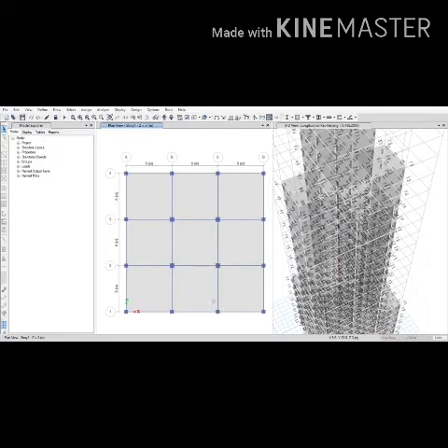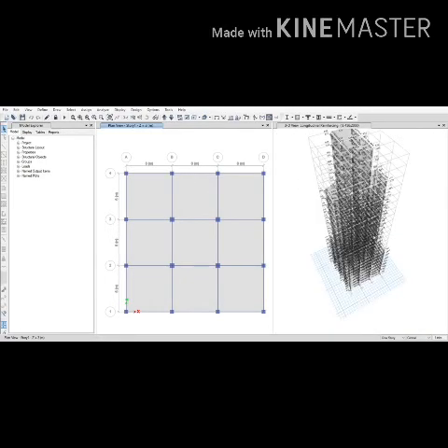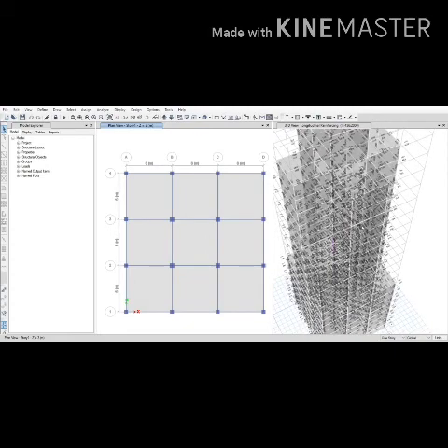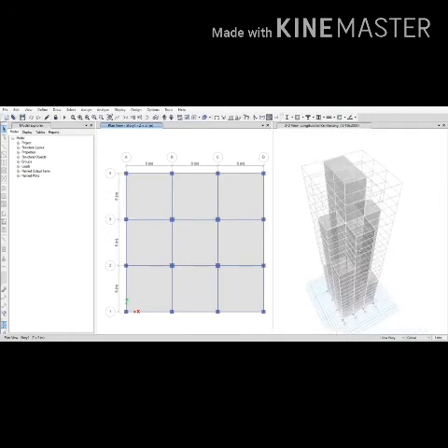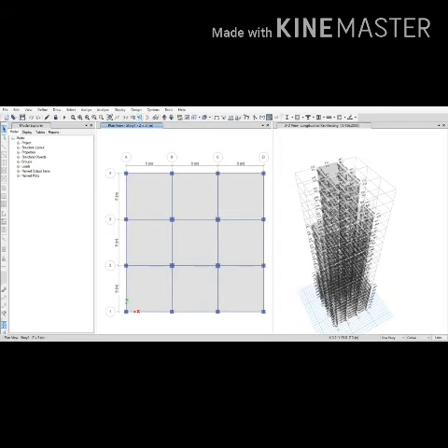And after this, you have to go to the start design check, and it will take some time, and we have to verify whether all the concrete frames have passed the design check or not. If not, you have to change the frame sections, or it will ask for iteration, because we have given alternative frame sections in advance. So for all the concrete sections, I went through two iterations. Finally I got a complete design check, and all the members are designed and satisfy the analysis.